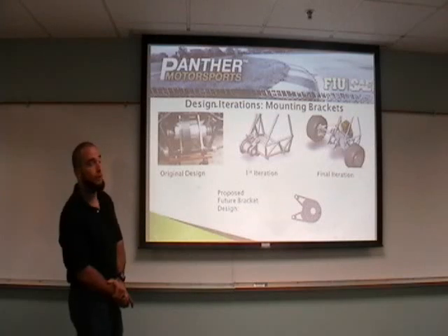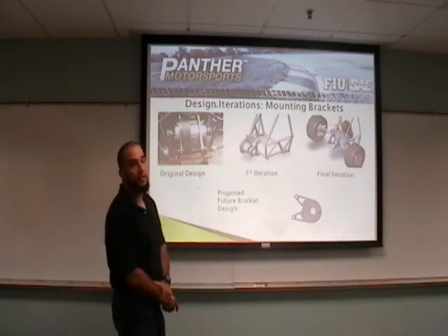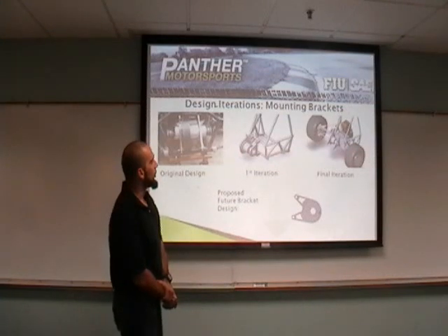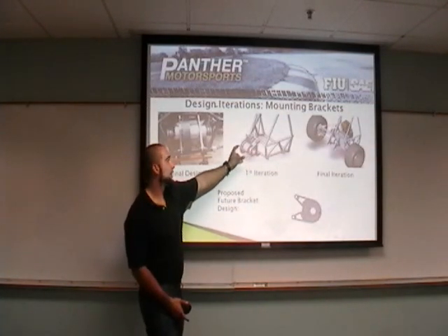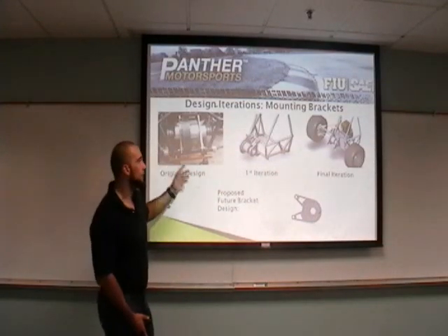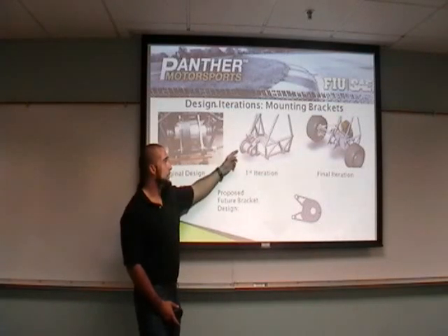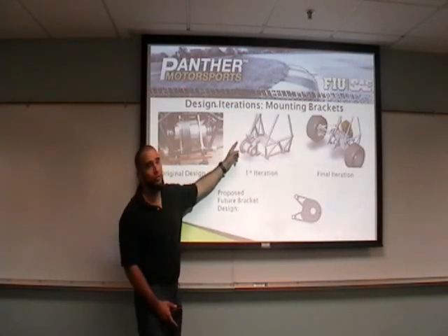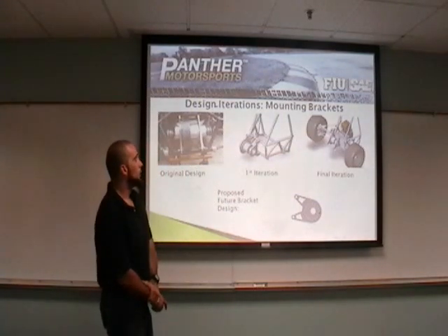which still allowed the chassis to leak. The first iteration that we have designed as a team is for the free-floating differential, a bracket which uses the same size bearings, which was also another issue for the 2014 season. One of the issues that we first came upon here was alignment of the differential as well as interference of the sprocket with the rear of the chassis tubes.